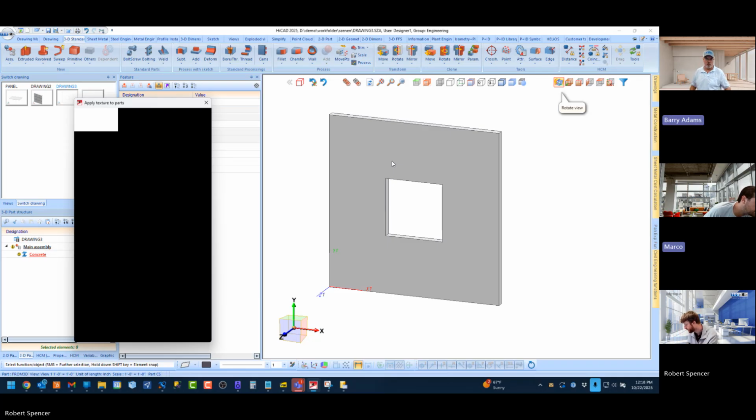Ooh, fancy concretes. Yeah, concrete. Well, when you said that, when you do a sectional view, whether you're extruding or when you go with that other function, they both perform a hatch where they used to not, or do they still not perform a hatch? No. You'll get the hatch with the extruded part. However, with the steel type part, it'll create the hatching per the material. You can assign a hatch to that material, where the extrude will give you just a general hatching setting.